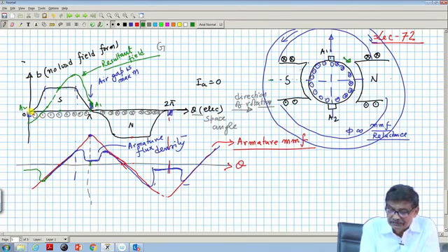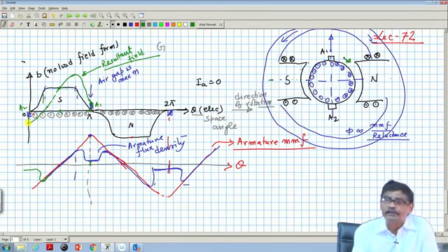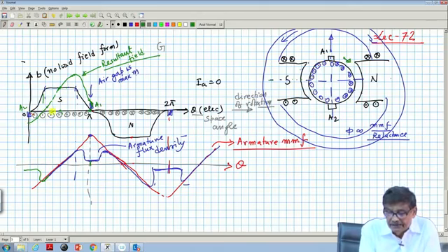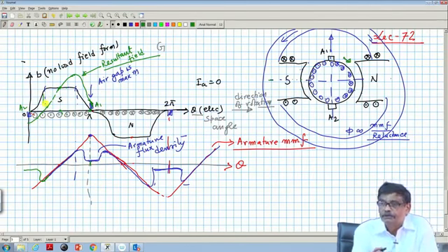This is the leading pole tip, this is the trailing pole tip. So, half of this one is the leading, trailing pole half, and here you see B's are high, the lines of force will be concentrated, and here the B value is less, means lines of force will be rarefied over the same area, lines of force present will be less and here it will be more.